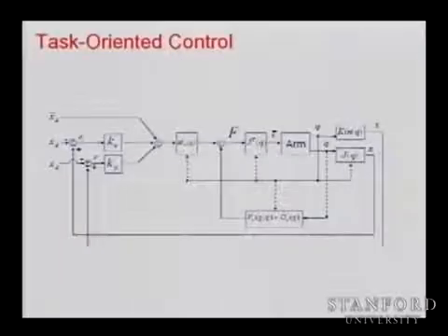Okay. So this is the overall controller. The overall controller is now compensating. It's the same structure that we saw before, but instead of looking at the system in joint space, we are using this J transpose to transform this into the end effector behavior. And now we are compensating for centrifugal Coriolis gravity forces that are modeled for your end effector.